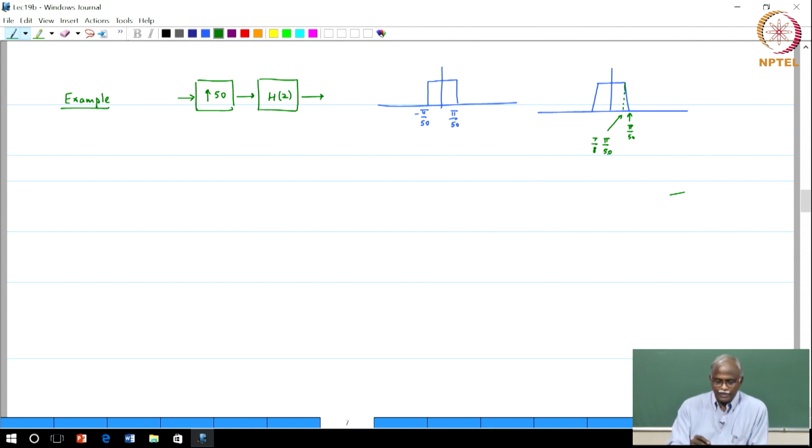If that is my specification, please run it through some filter order estimation formula. I am sure you have done this, and assume some reasonable ripple for the pass band and stop band. You will find that this gives you a very high order filter, because the transition band is very sharp. Of course, that means you will have a lot of multipliers.